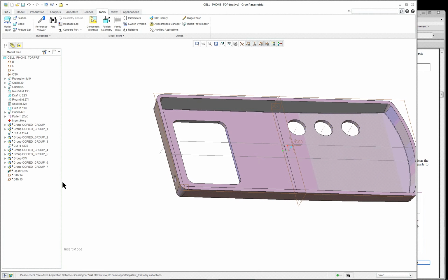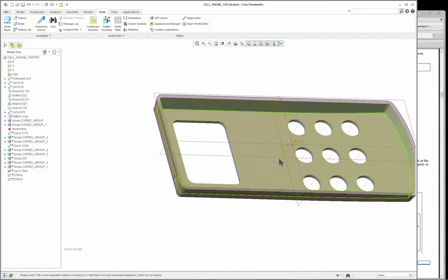This is kind of odd. Looks like they mirrored it. You might try another method here. I think it would be better. Do a pattern, table pattern maybe, or just a pattern and then remove the ones that you don't want.